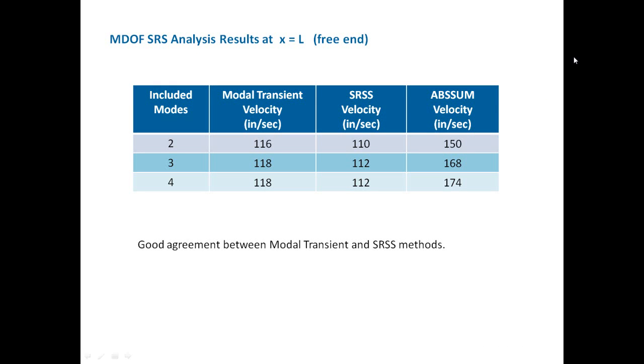So this is a roundabout way of saying, if you're in a hurry, you don't need to do the synthesizing of the waveform. You don't need to go through and do the modal transient. You can just do this shortcut method, the multi-degree of freedom SRS method.